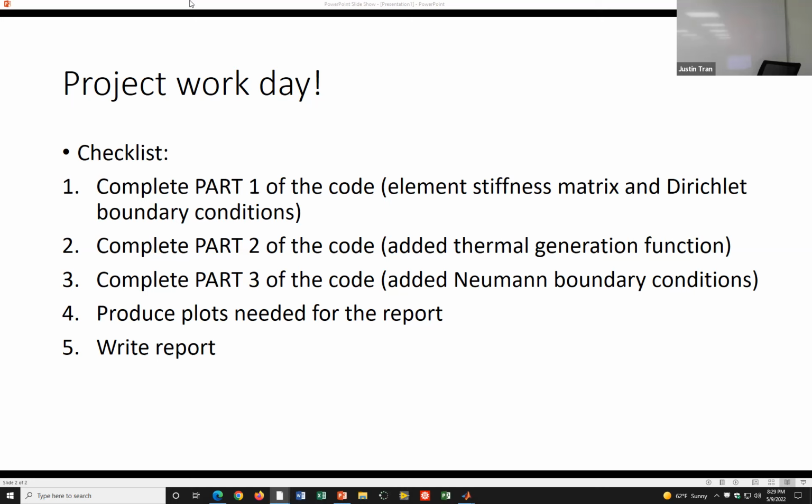Yeah, so there's always going to be some error because if you open up one of the figures right now, so let's look at figure 5 and 6. So what happens sometimes is that when we apply the Dirichlet boundary conditions, this is an edge right here. This is an edge. We have some nodes that are going to be shared between those two.